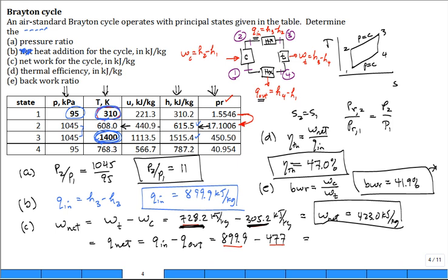But if you get the compressor to run well and the turbine to run well, this is a great power plant. It produces a lot of power for little weight of the equipment. And that's why they're used in flying machines, in helicopters. Gas turbines are the primary source of power in helicopters. Tremendous power, low weight. Jet engine, exactly. Now, we just talk about stationary power plants right here, but okay.